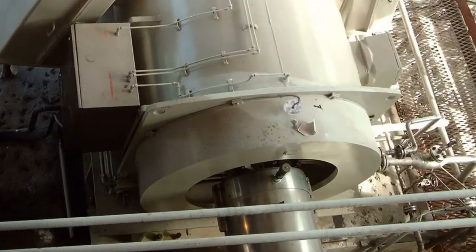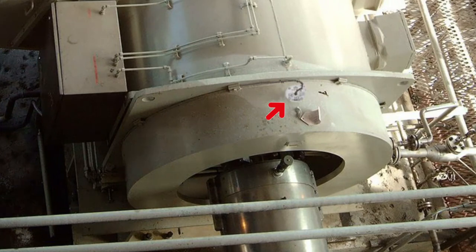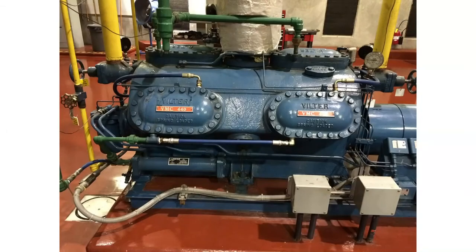Especially for vibration measurement in the kilohertz range, it is recommended to choose only stiff components for mounting, and to avoid joints between components, because they may attenuate higher vibration frequencies. Massive cast iron parts are usually good points for attachment, whereas light components made of sheet metal, or plastics, are generally not suited.